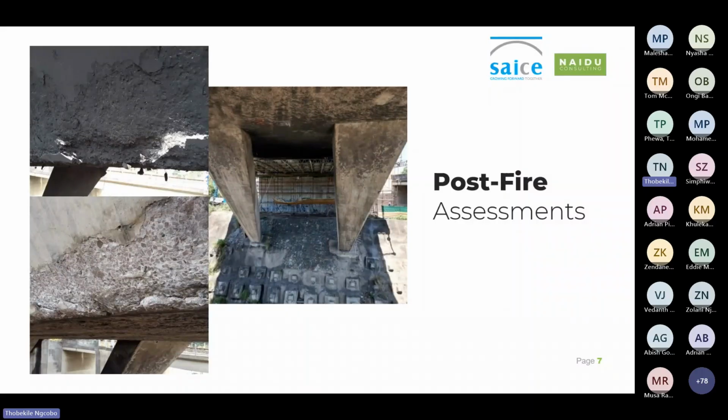Traditionally, fire damaged structures are assessed through methods such as visual inspection, color observation, and core sampling. These approaches can provide valuable insights into the extent and nature of damage. However, they also have certain limitations. Visual assessments can be subjective, relying heavily on experience, while core sampling and other destructive test methods are selective, time-consuming, localized, and can cause additional damage to the structure.